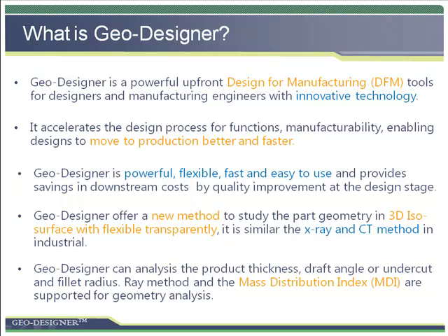The analysis result of Geo-Designer is very rich compared with any CAD system, such as product thickness, mass distribution, draft or undercut angles, fillet radius and more. We have introduced the mass distribution index, which we call MDI, to industry. This is a very important concept in the design.